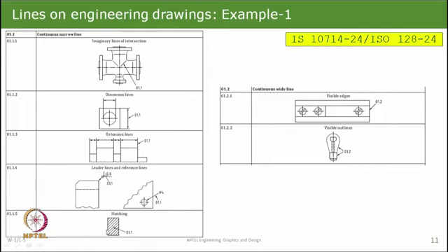This is what is called hatching, and this is what is called a visible outline. So, this is a typical, say, a bulb which has got this glass envelope, and what this line shows, a thick continuous line, is that this is the outline of the object. And that is what I had shown in that first example that I gave a few slides back. The object lines, the outlines, were shown by a thick continuous line.